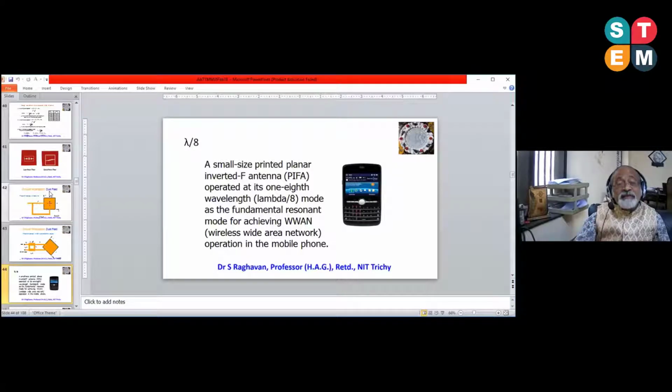You can understand the subject. Designing will be in your thumb. It is not going to be difficult. The other part also, you can do it very easily by knowing the impedance, characteristic impedance, and using Wheeler's curve and other nomogram, you can find out exactly up to the third decimal of millimeter or micrometer. You can design the components, the length and the width, or the whole world behind the design concepts.